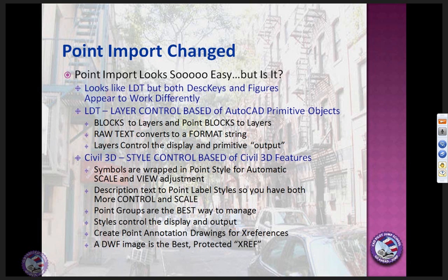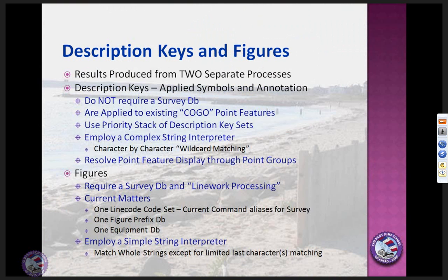If you're going to use the points to annotate a site map or sit underneath things, you're going to want to generate the points themselves in a completely separate drawing or drawings to use as XREFs. The other quick and dirty way to do that is to generate from that drawing a DWF file, which you can plot to, and use that as an image, as an XREF. So an IREF, so to speak, is one of the better ways to get all that printed out and track it and redline it and make sure it all turns out well.